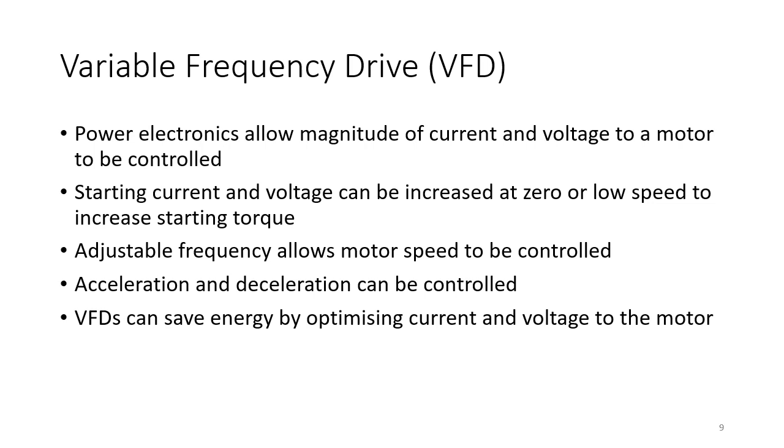But the idea is, by adjusting the voltage and current, and ultimately by adjusting the frequency, this allows us to control our motor very accurately. Now, VFDs often have additional technology in them to have startup and deceleration and acceleration ramping, so we can also control the acceleration and deceleration. Now, ultimately, that will be controlled by physics.